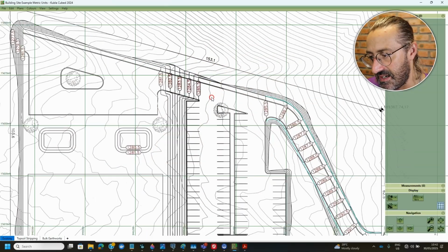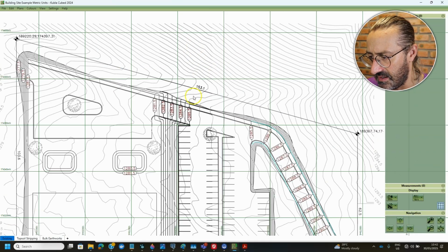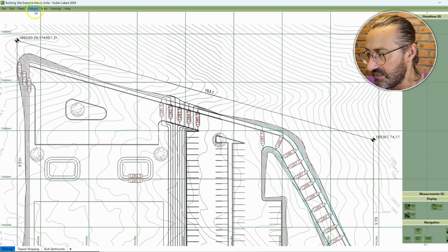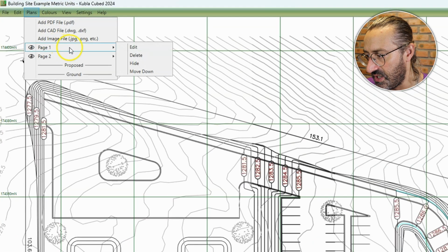It looks fine for manual tracing, but for PDF vector extraction, we automatically try and join PDFs across pages. If there are lines that cross a page boundary, we try and automatically join those based on a tolerance. So in this case, you can see that it's not going to work very well. So what we do is we'll change the crop to make sure that there's just a small gap there.